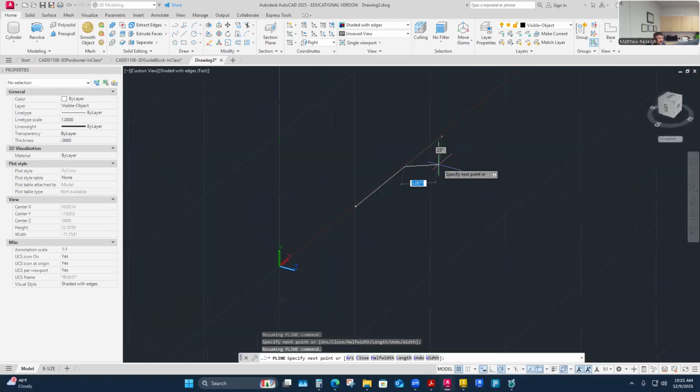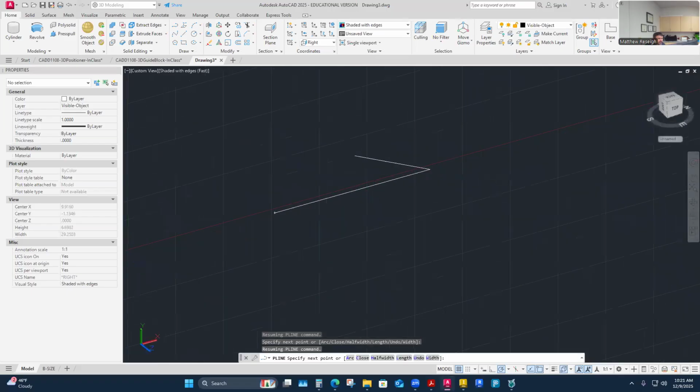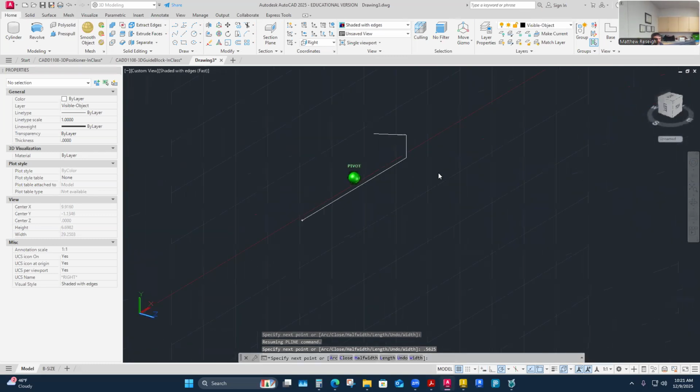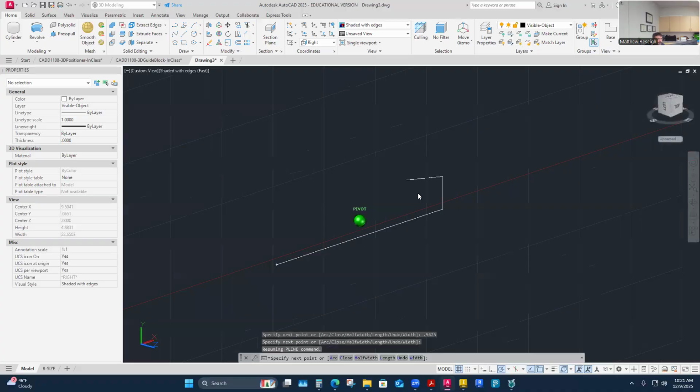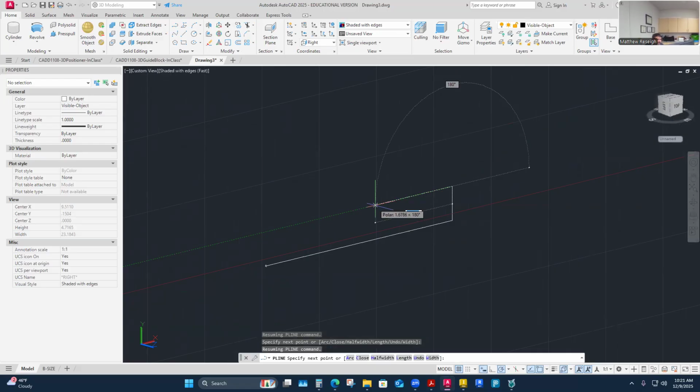And what it allows me to do is kind of like pictorial drawing. It allowed me to be on this grid plane, drawing the profile of the shaft. So in this direction, the overall diameter now is 1 1/8, but I want just the radius of that. So that is 0.5625. It's 9/16. And then it comes back this way with all the details. I've rotated this, so it looks like I'm drawing in 3D, but really I'm on a 2D plane in 3D space. This one I don't know. It wasn't given on my drawing.